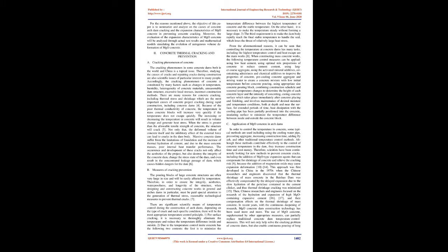Measures of cracking prevention. The pouring blocks of large concrete structures are often very large in size and will be easily affected by temperature. Therefore, in order to ensure the integrity, aesthetics, waterproofness, and longevity of the structure, when designing and constructing concrete works in general and arch dams in particular, special attention must be paid to the generation of thermal stress and reasonable technological measures to prevent thermal cracks.